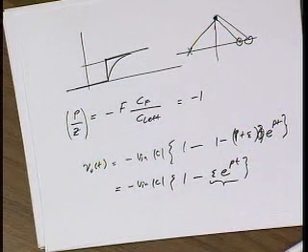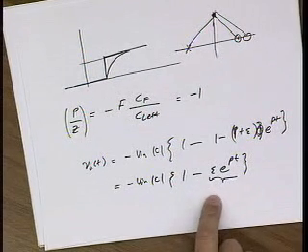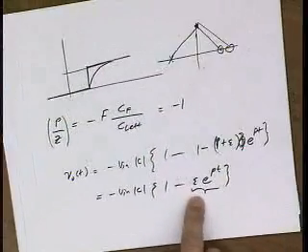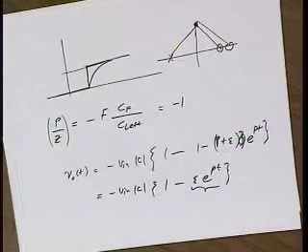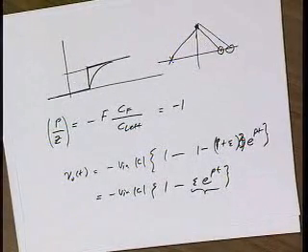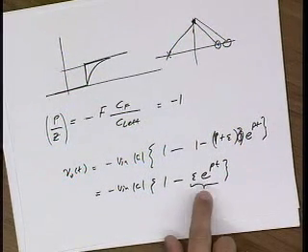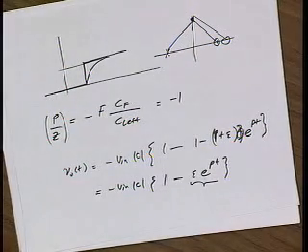So let's say that through a really great layout, I make epsilon 1%. And I'm really proud. I go around telling everybody I managed to get my pole and zero accurate to 1%. Well, if you're designing a scope, the human eye is not going to see a percent. So even though this term is still there, you just don't perceive it. On the trace, it looks like a perfect step function. But now you try to sell this to your customer, and your customer says, no, I want 0.1%. It's hopeless. You're never going to get 0.1%. So then you're going to have to wait. Okay, we'll pick that up next lecture.